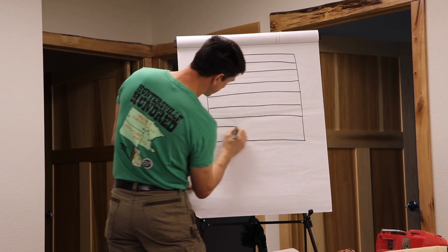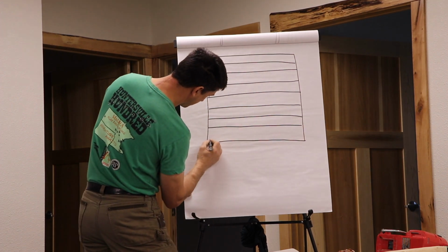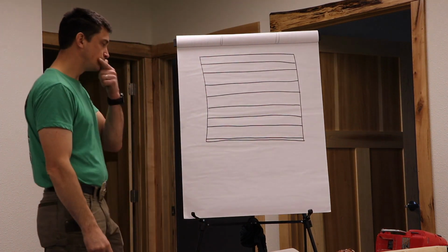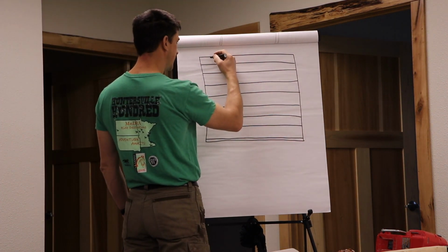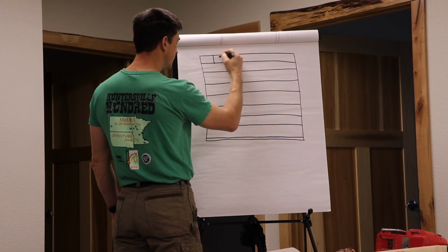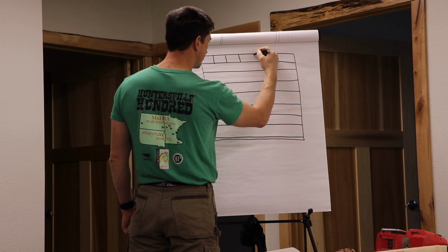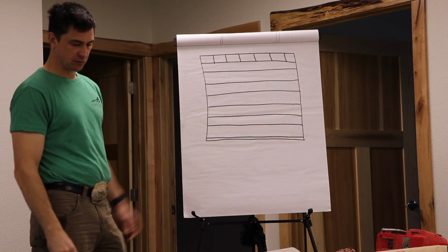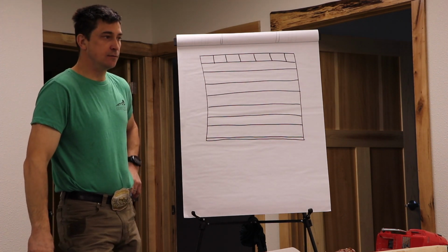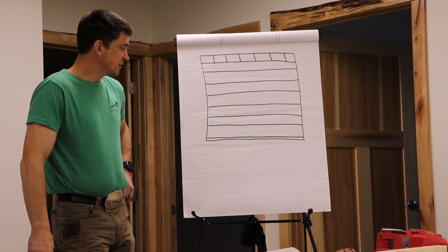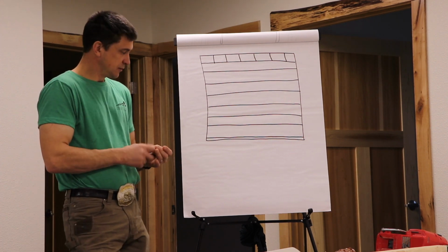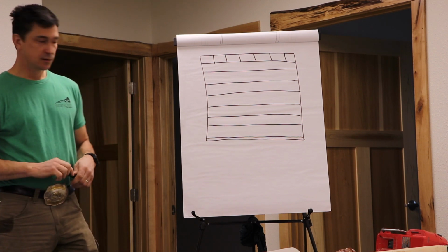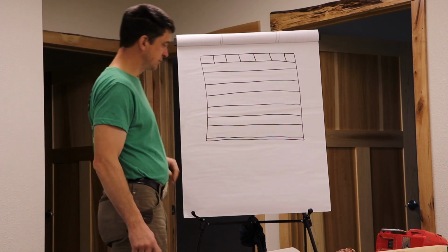So this is one that I see all the time. Okay? So then we're like, oh yeah, I don't think that we can leave it like this, so we'll throw in our blocking here. But, oh, then that one works, because it's right there, that'll carry our wall. This is the framer that isn't thinking about the plumber, the electrician, the HVAC guy, or the insulator. Okay? So you just created this closed cavity.